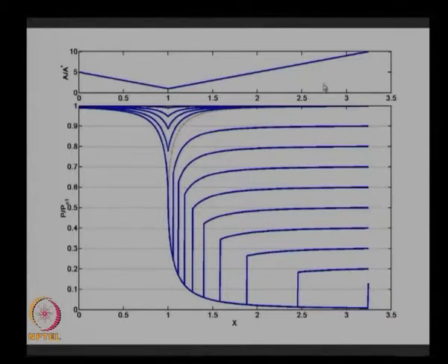Okay. I did not want to choose this exact nozzle because you can just use this plot and give me answers. I picked a nozzle with exit area as A by A star of 3. This happens to be 10. Okay. I just picked some other case. So all we know is if I want to decrease the exit pressure, my shock has to go more downstream. Okay. Now we will go back here.